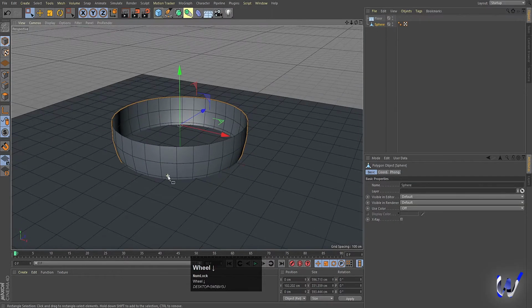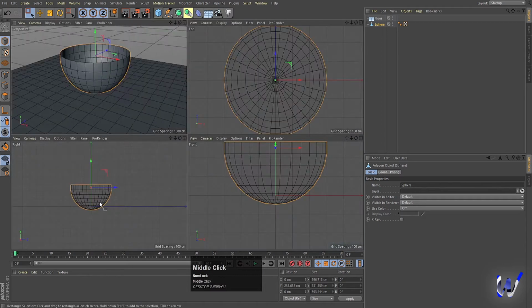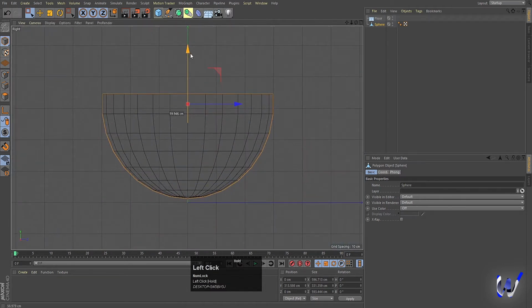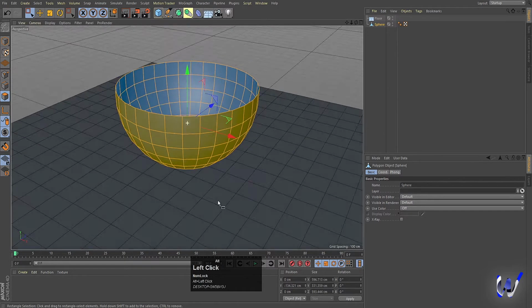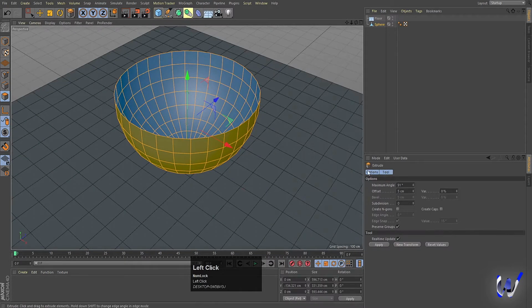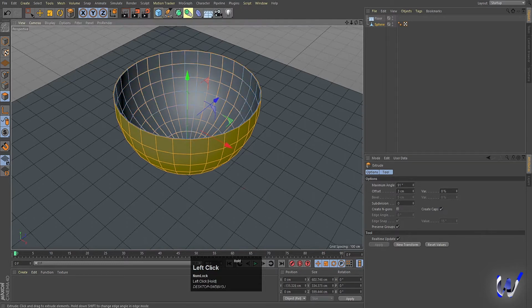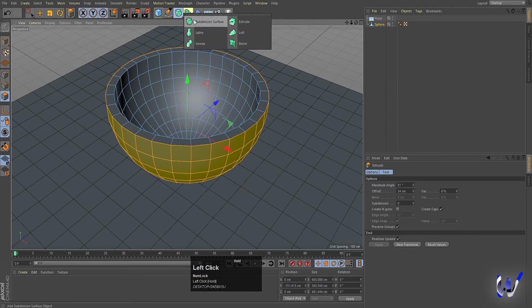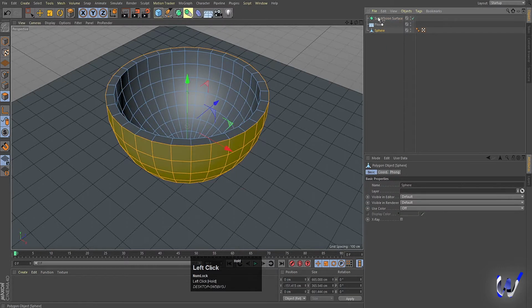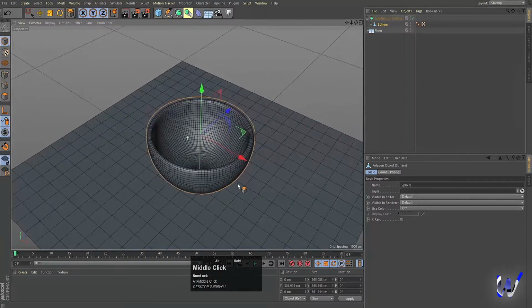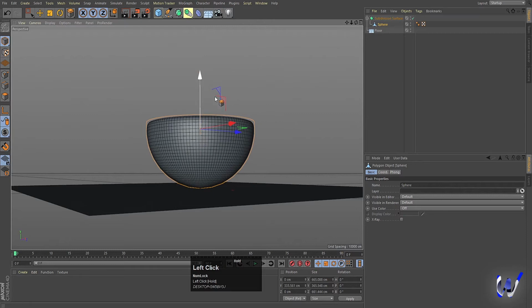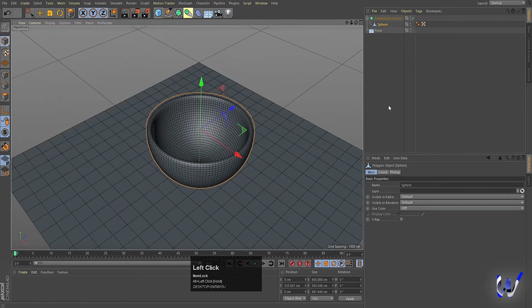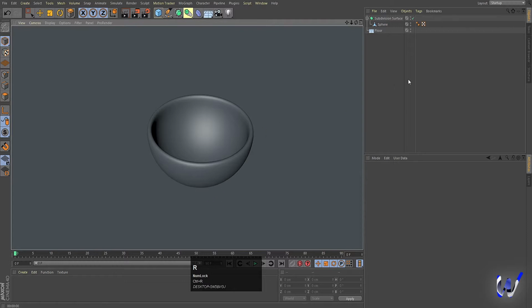Now select this sphere. Let's move this over here, like this. Now select those points, hit Ctrl A, right click and make it optimize. Select those faces, hit Ctrl A to select all the faces, right click, choose extrude, and make sure that you are choosing create caps and extrude it outwards. And then bring in our subdivision surface and select this sphere and move it inside this subdivision surface. Let's move this sphere something over here. So if you see, we will get something like this. If you hit Ctrl R, we will get this kind of shape.